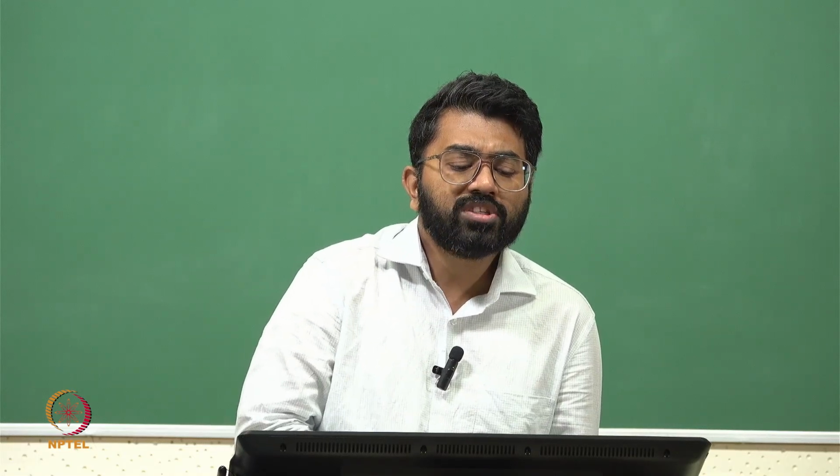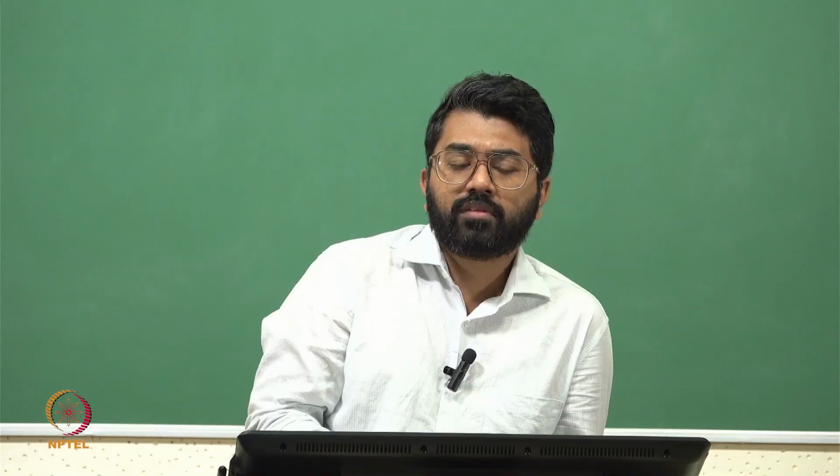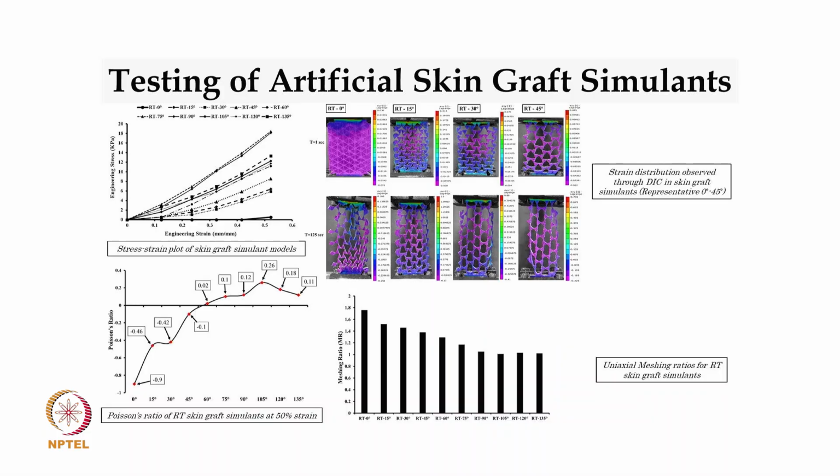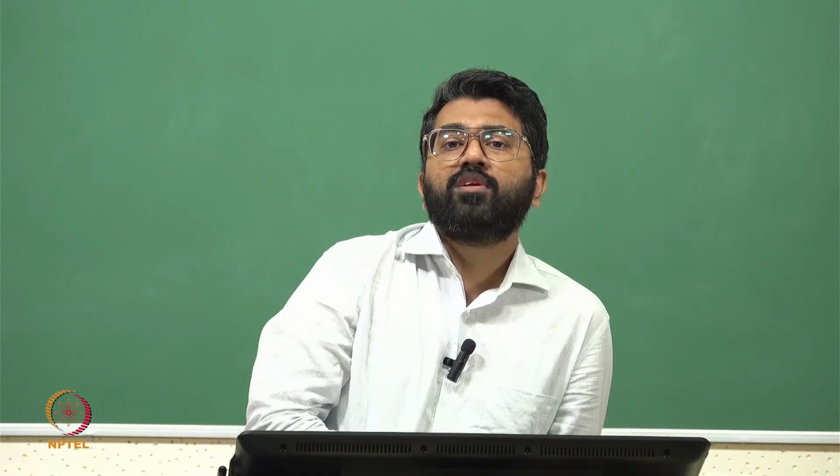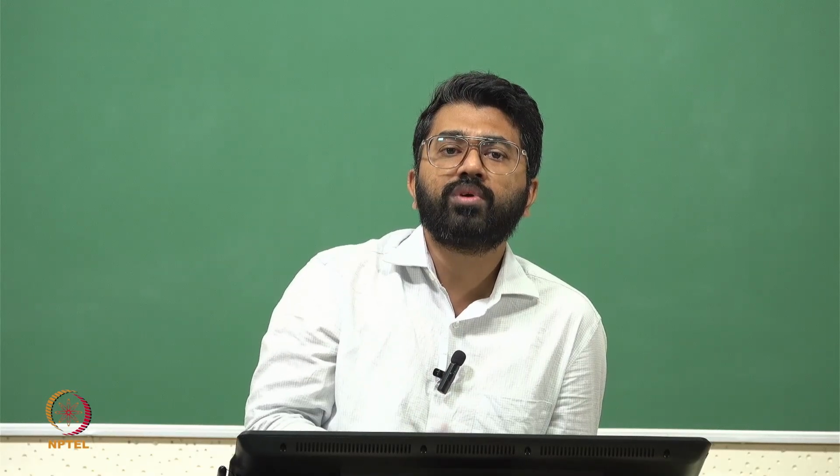We also compared the engineering stress, how much overall stress is developed in each of these samples through a UTM test, right. So we have plotted the engineering stress versus engineering strain. We've also looked at the digital image correlation results on the right side, the imaging based results, and we are seeing places where you see a lot of holes or voids within the final stretched specimen when you try to expand it. These voids are not desirable, right. If you have a lot of void between the burnt skin, the cells are not going to proliferate and the skin is not going to heal that quickly.